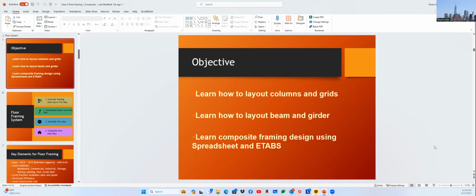With all the floor framing layout, we need to know how ETABS works. Users need to assign all the slab as a metal deck and concrete slab, then the orientation of the slab, and assign the loading on the slab, which is our design load: gravity dead load, superimposed dead load and live load. With all design loads and boundary conditions, we should be able to analyze the 3D framing and calculate the shear force and moment. So we're gonna get into that later.